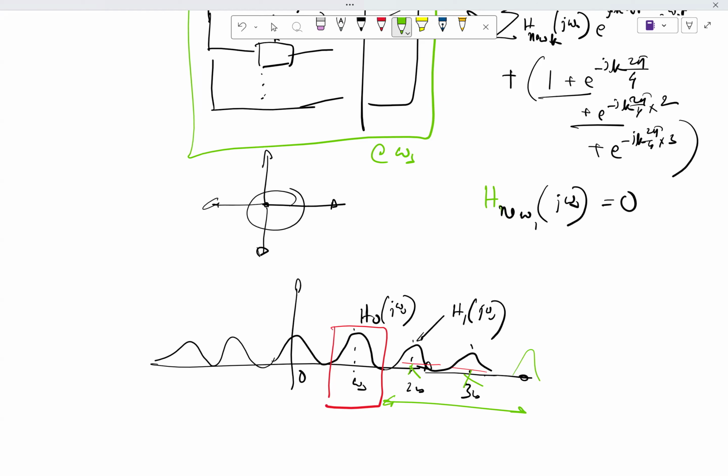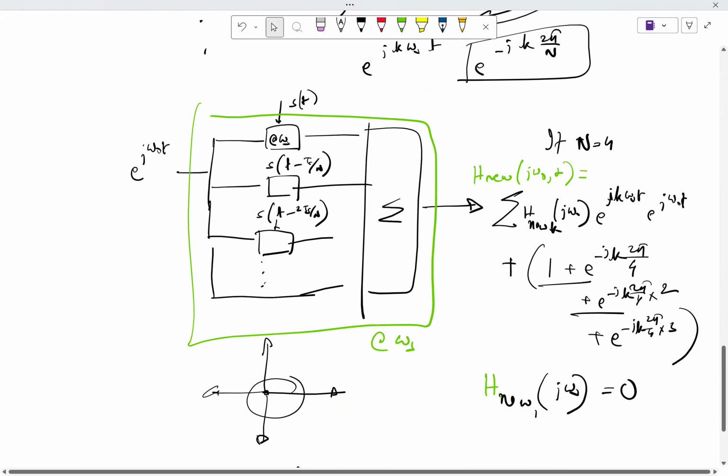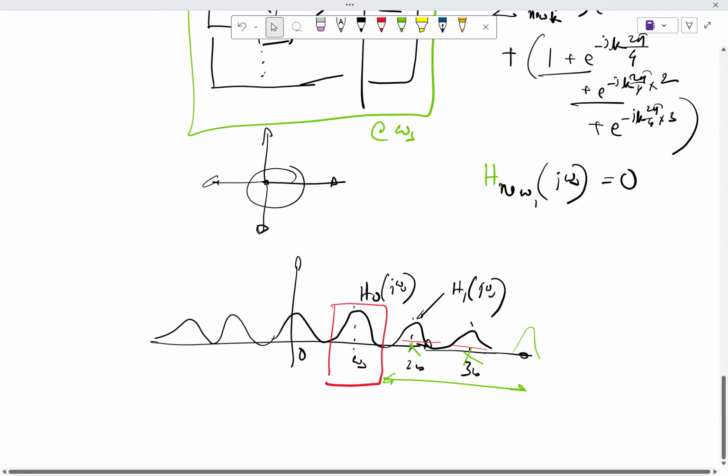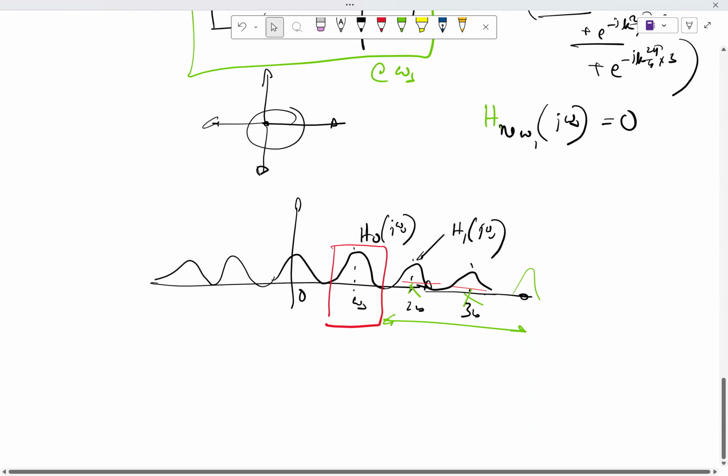So the good thing about having multiple phases, n becoming high, was that we get sharp filtering. But having n high alone was not sufficient because we were getting additional nearby peaks. By putting n high and replicating the same setup multiple times, shifting it with respect to time and adding them up, we should be able to get rid of these sidebands also. Hence it makes our life easier from a system level perspective if you want to bandpass filter. Make sense?